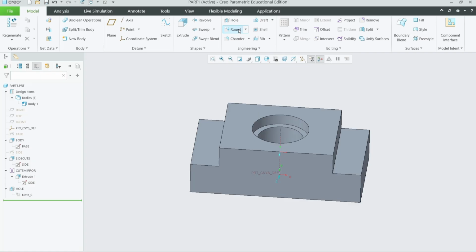The chamfer feature replaces a sharp corner with a flat angled surface, and the purpose is that it removes sharp edges, usually for safety, and simplifies assembly by guiding mating parts like pins or screws, and it's just easier and cheaper to machine than a perfect round. It's often specified as a distance by an angle, for example, 1 inch times a 45-degree angle.